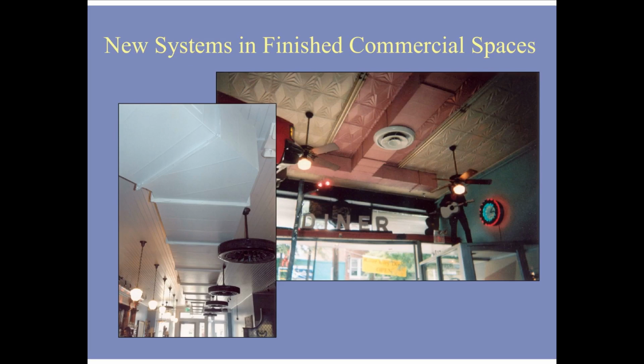Be aware that the shape and size of the ducts will make a difference on the extent to which these new intrusions affect the historic space. Rectangular or square ducts can often be attached closer to the ceiling and fit in a smaller space than spiral. However, the hangers used may create a more cluttered appearance and attract more attention.